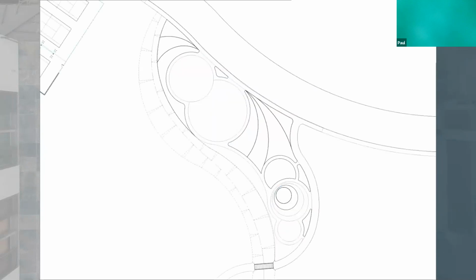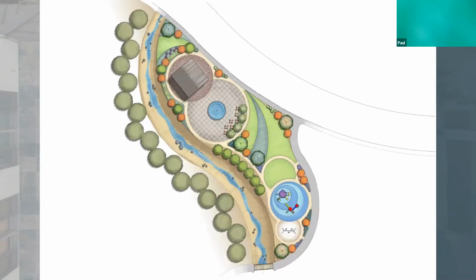Because I exported those hatches as solids, I didn't have the line work with it, so I also exported just a PDF with my ground plane line work. And then finally, for the pavement items, I turned those solid hatches into patterns and then just exported the pattern so that I can basically overlay these on top of the color and have that pattern there.